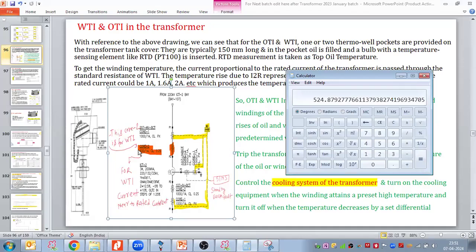That I understand. But why are we going for HV bushing CTs of 1000 ampere? Actually, again you have the options. You can reduce this 1000, you can go 600 as well. Here we have taken more. This is a grid substation project, so we have followed the grid technical requirement for the CT rating.